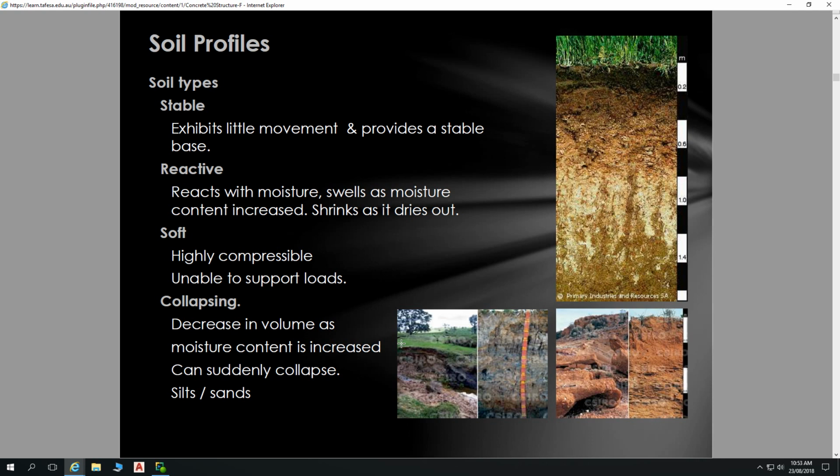And certainly the main motivation is to ensure that the buildings aren't cracking, and that idea of a raft slab is to enable that, but still we don't really want that to happen to a large extent either. We don't want buildings going on a large tilt and so on. Hence, in some scenarios where we do expect that sort of thing to be happening, yes, you do piers down into solid foundations.